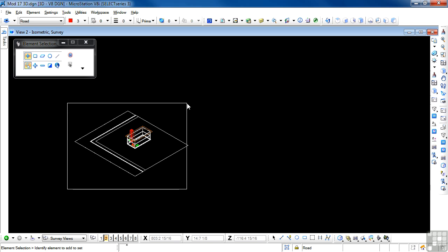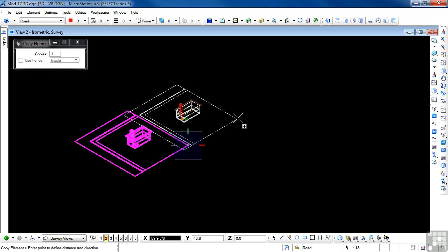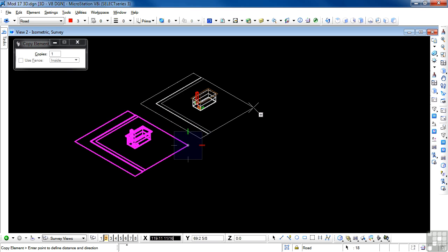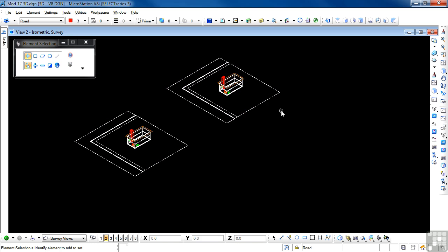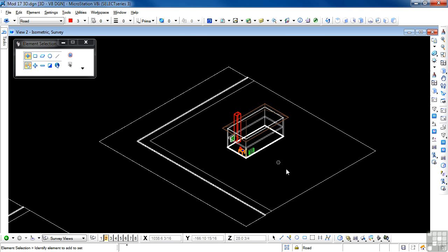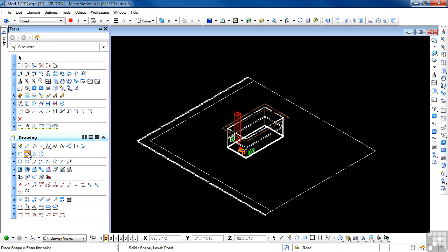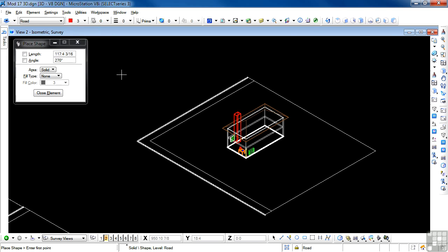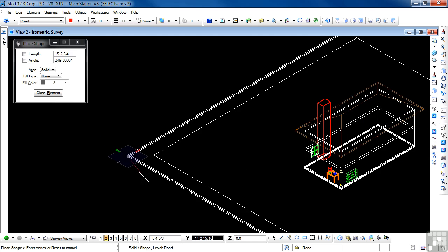Now I'm going to make a copy of this. Copy it from there. You can do this straight ahead, but in top view, I need it to be precise. There. Now I'm going to do some surgery on this part of the drawing. I'm going to delete my roadway and I'm going to draw another one. I'm going to go to Place Shape tool. I'm going to start here where the roadway starts. I'm going to go that way.